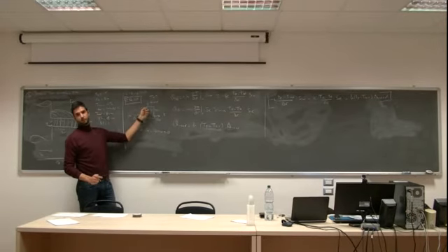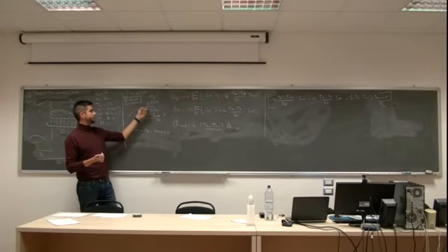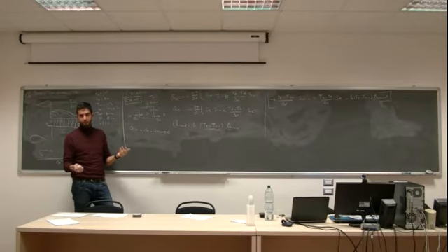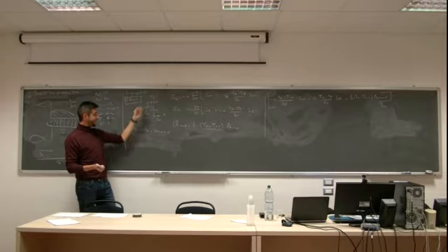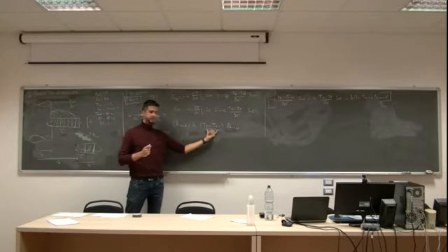So you have to respect the direction that you have decided here. You think that the temperature of the node will be higher than the temperature of the air because it's leaving the convection. Because it's leaving, here is negative. I assume that, so I put it this way.